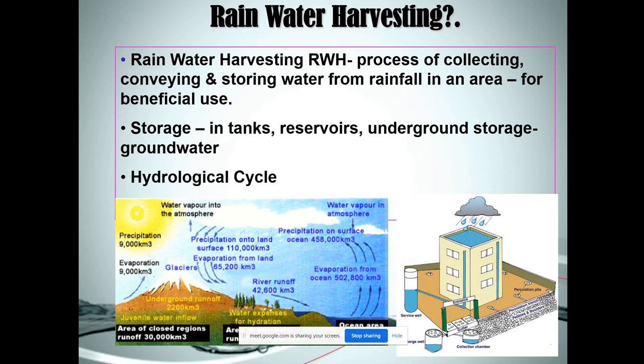Let's take a look at the water cycle. The water cycle has many parts. First one is precipitation, infiltration, evaporation, and surface water. Rainfall definitions: intensity, based on quantity per time of rainfall event; duration, period of time for the precipitation event; average annual and monthly precipitation, average rainfall over a 1 year period and monthly intervals, and usually based on 30 or more years of data.